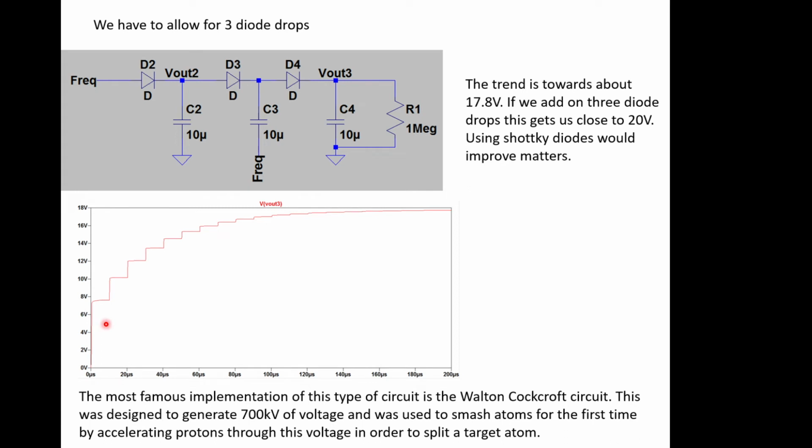And then, because we've got diodes in this system, we will have to allow for 3 diode drops in our system to predict our total voltage at the output. So it's going to be whatever the theoretical voltage would be, which we said was maybe 20 volts, but we're going to drop 3 voltage drops across here. So you can see why the expected 20 volts is actually a bit less in this case here. So these are using signal diodes, silicon diodes.